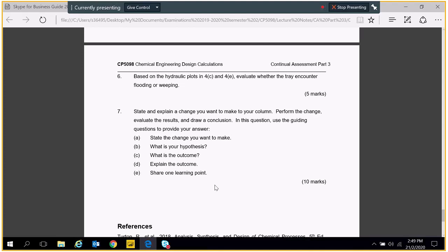From this simulation, you learn, for example, that changing the design objective in terms of benzene purity will affect the rate of heat transfer in the condenser and the reboiler. Not only that, this also suggests that the rate of heat transfer between vapor and liquid for each tray is affected. And the K factor is also affected. Remember Y equals Kx.